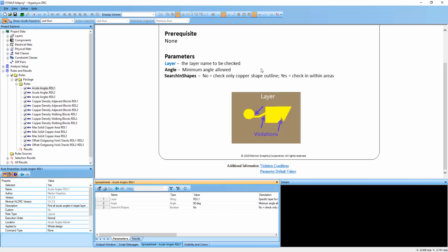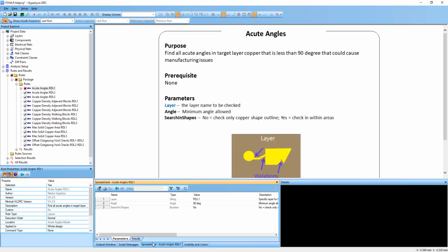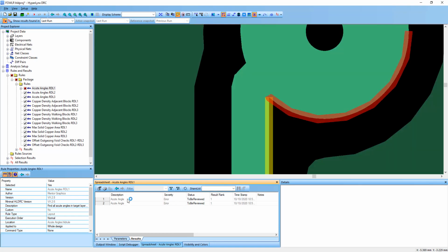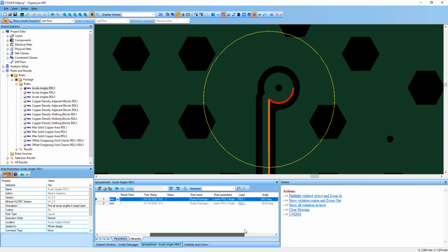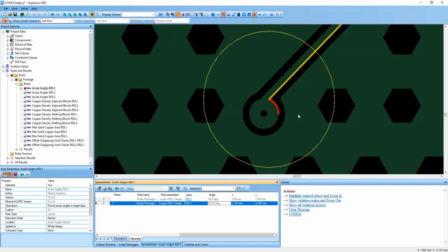In package designs, acute angles are manufacturing showstoppers. If the angle is less than 90 degrees, it is possible a teardrop can't go in and the PCB will have repercussions when fabricated. This rule will point out the angle and the location in the design where it finds the violation. Natively, a PCB layout tool would not detect them, and these types of acute angles would be found